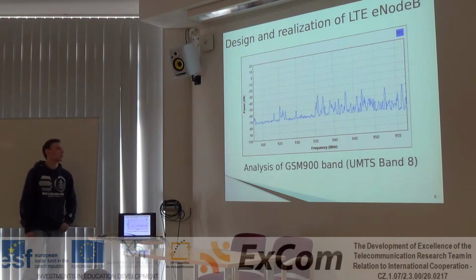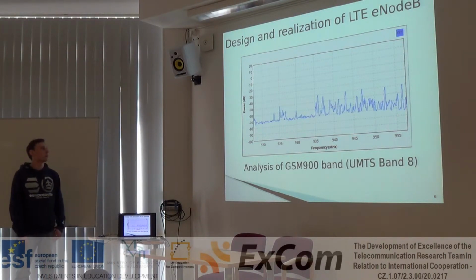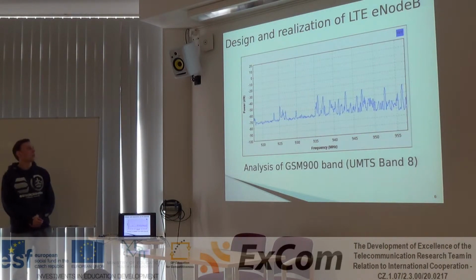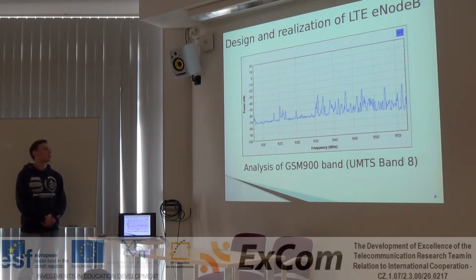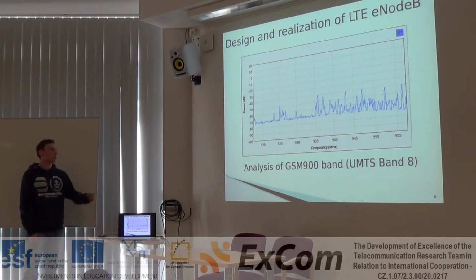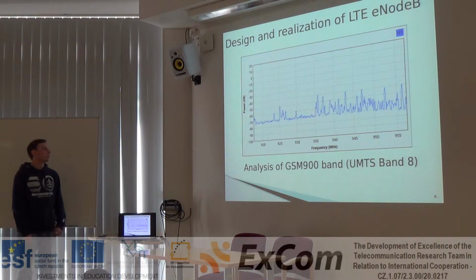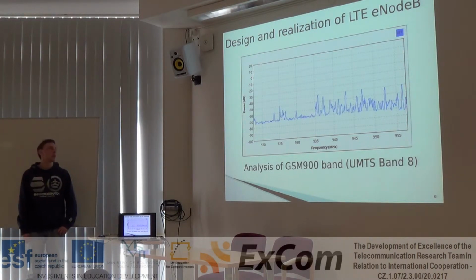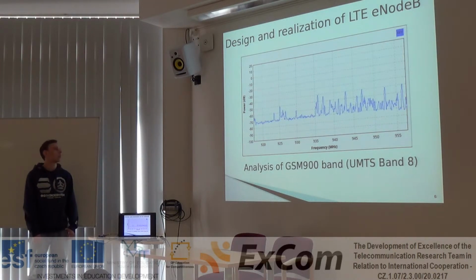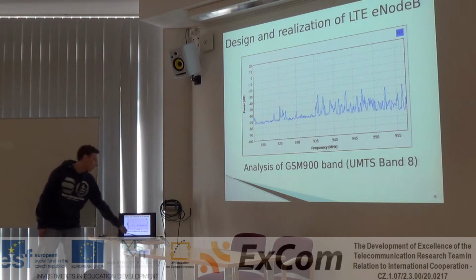There is an analysis of the used bands in the Czech Republic. Namely, it's band GSM 900. So we cannot use this UMTS band 8 in our configuration for OpenLTE because it can interfere with this network, and also our mobile phone couldn't find our OpenLTE network.